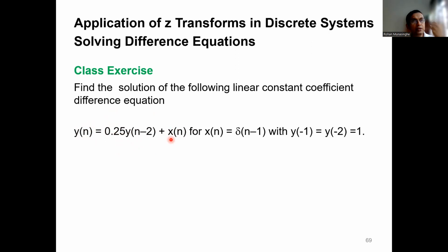Now, how do you get this kind of difference equation? You can imagine a situation where there's a system and there is an input to the system and then a response out of the system. In continuous time, you can model this using a transfer function, input, output, x[n], y[n]. And then when you discretize it, you bring the transfer function, or ordinary differential equation, into a difference equation.